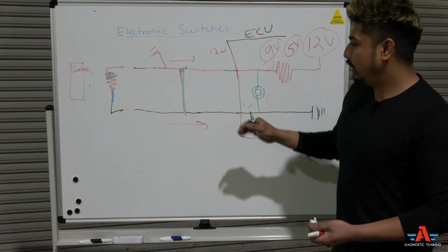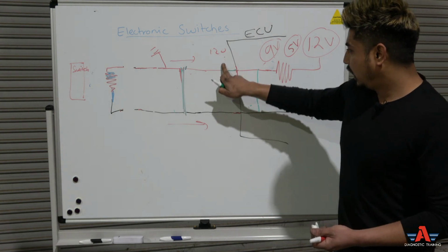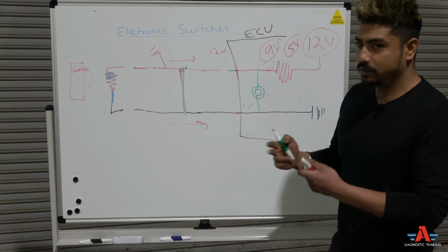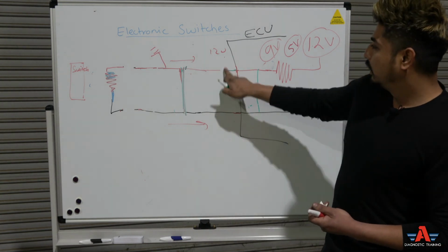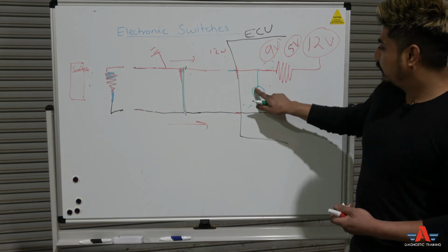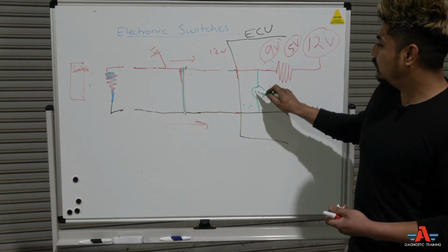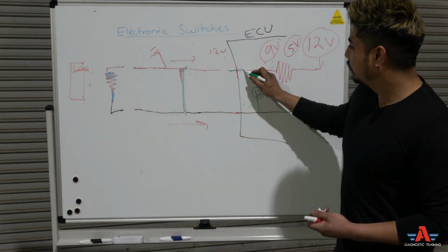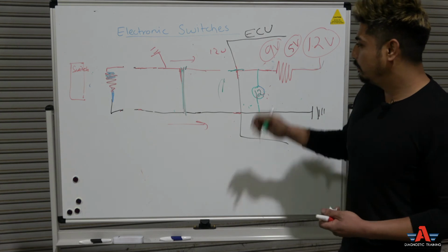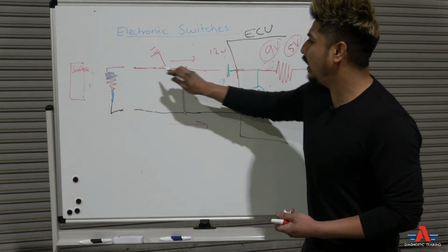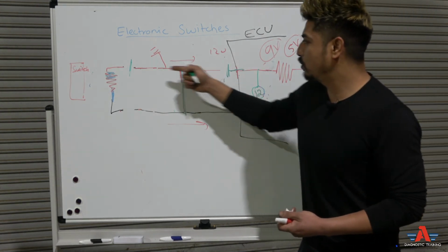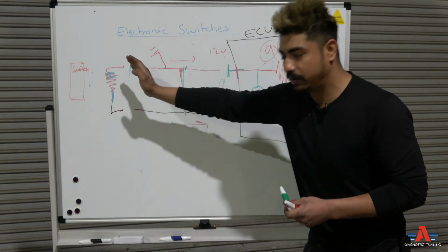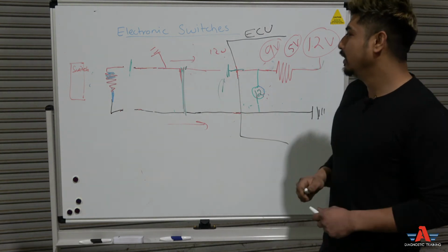Now go to the computer, and cut this wire right here, right at the computer. Obviously keep some length so you can solder it again. Cut that wire. Now what's going to happen? If the short is there, this is going to change to 12 volt, because 12 volts come in through the resistor, no path to ground. Means the problem is between here and here. There's some short between the wires, right? Wires between the computer and the switch, right?